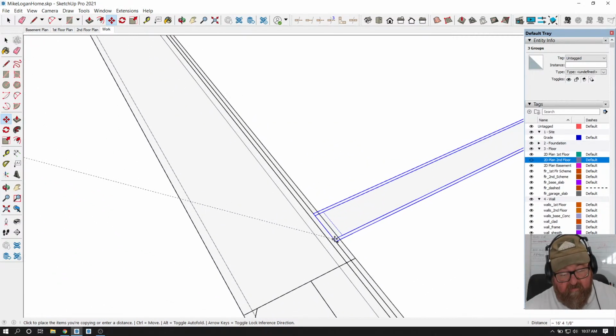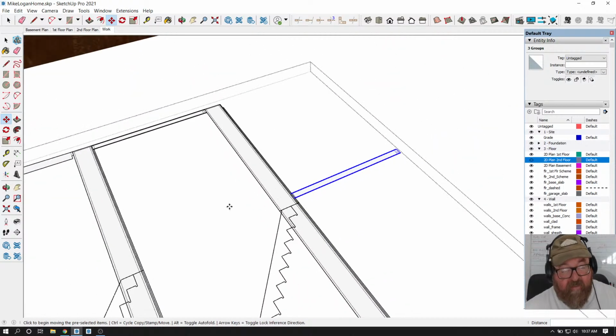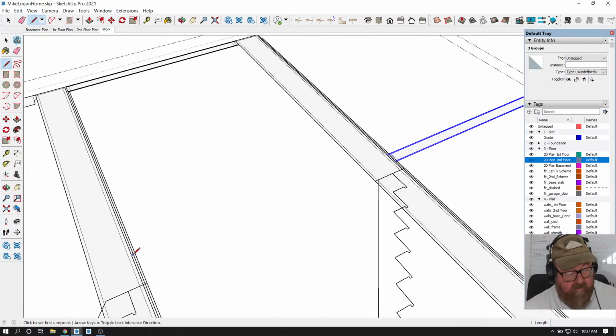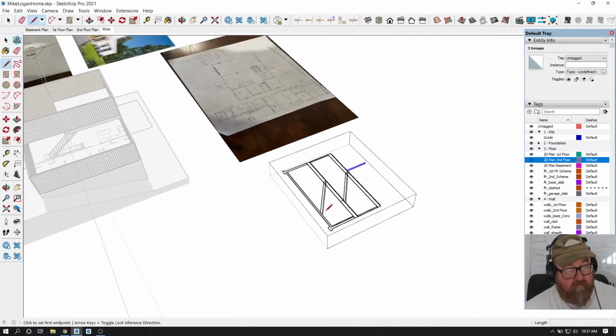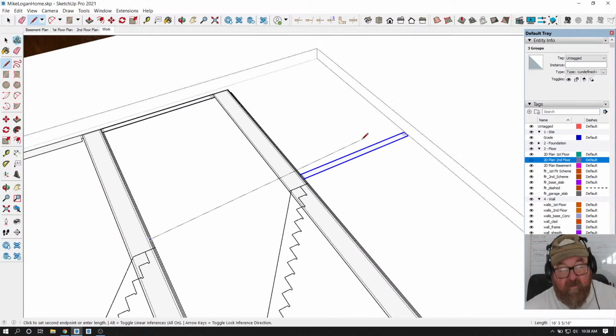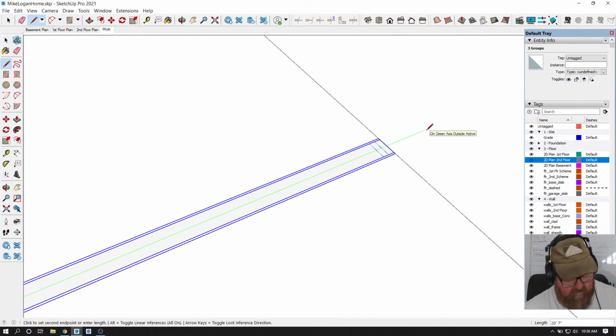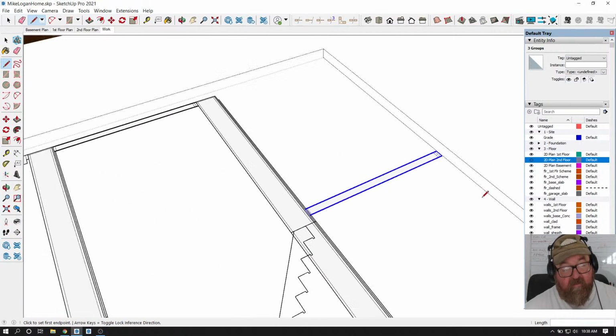But see, it goes on the subfloor, not the finish. The finished floor will be butted into that. So now I can measure from here. Let's see. I think the difference here is I'm setting my two-dimensional floor plan on the finished floor, 19.7. No, that's what I had.